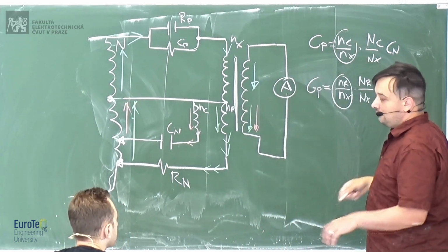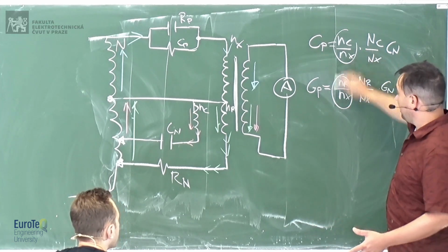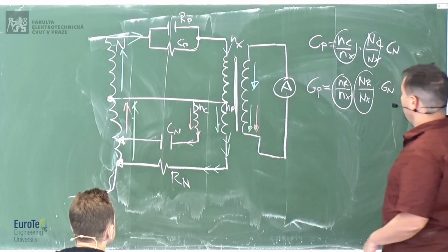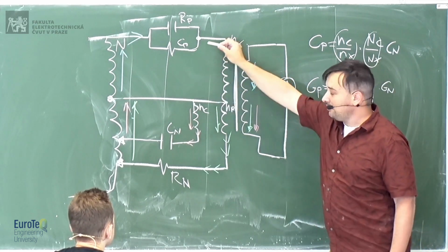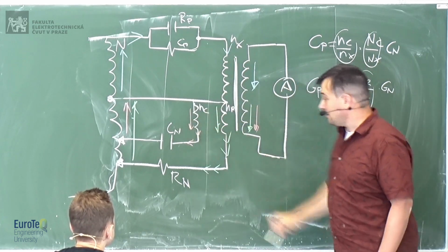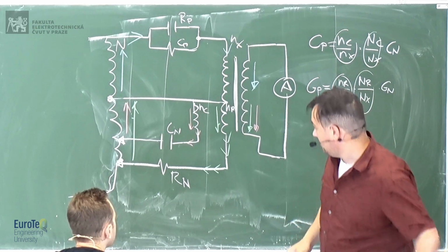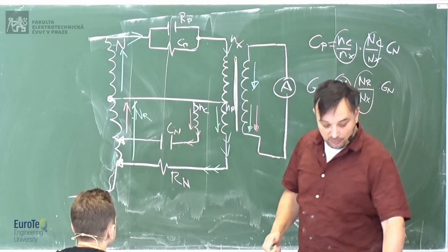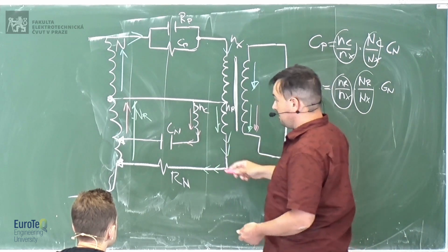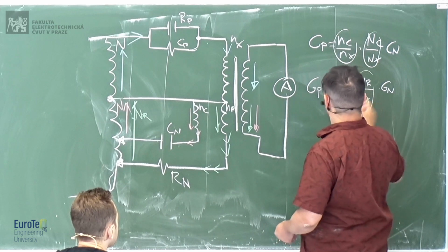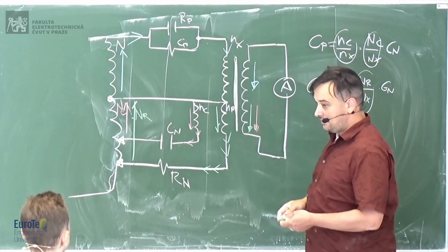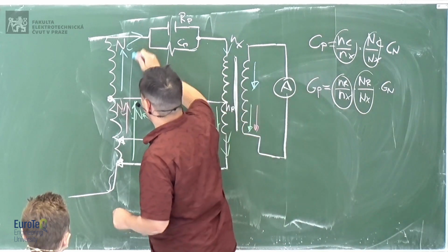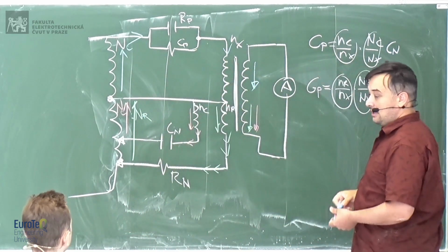Yes. Again, you write down all the equations, you solve them, it's just mathematics. So this is the ratio of the turns on the transformer. These are the numbers which are giving the voltage on the unknown impedance, and the known capacitance and the resistance. So here you have an, how we call it, an R. So here we take some number of taps that are proportional to the voltage to feed the resistance, and we call it C to feed the capacitance. And then, of course, we have a fixed number, NC, okay, which are feeding the unknown impedance.